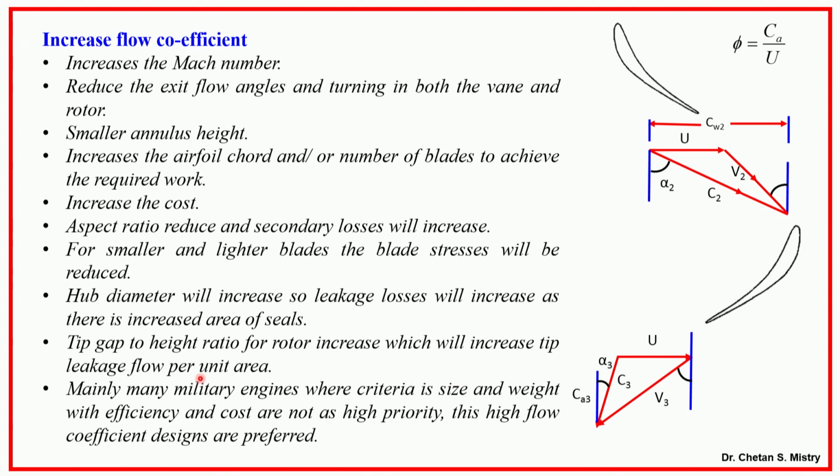My tip gap, the height, is subjected to tip clearance losses. What it says is, mainly when we are talking about military applications, where our criteria are size and weight, with efficiency and cost not a major criterion, under that condition it is preferred to move with a high flow coefficient design.